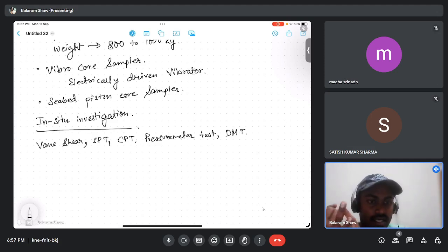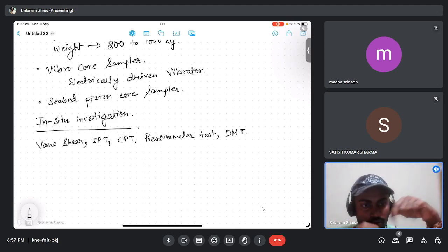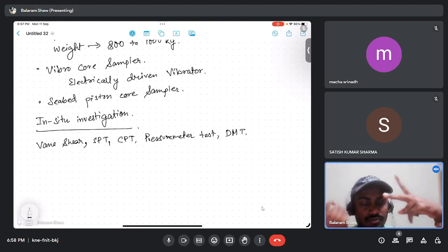In the second assembly, the CPT rod consists of a tube, which is wound around a circular frame. For penetration, the reel is rotated, and thus the wound tube gets unwound. The CPT assembly is then pushed into the seabed, and after it contacts the seabed, the tube is first straightened before being pushed into the seabed. Then with the cone penetration test, we get two things.